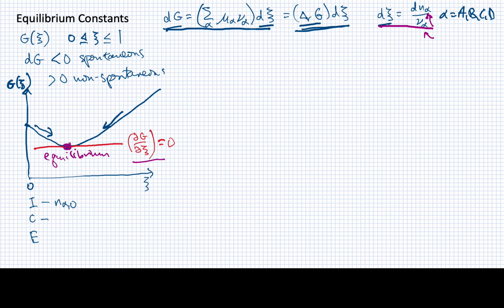The change would be the change in that reactant, all right, which we can write as the stoichiometric coefficient times the change in this reaction parameter. And then the equilibrium value is the sum of these two, so it would simply be nₐ₀ plus νₐ dξ. All right, and in this case we're using that plus or minus convention. For reactants this will be negative, and for products it'll be positive. But that's really all we're doing here.